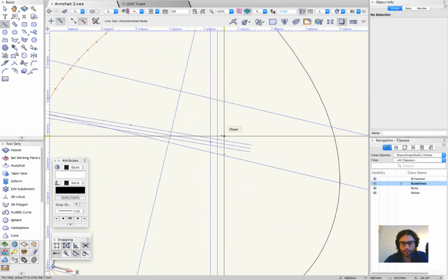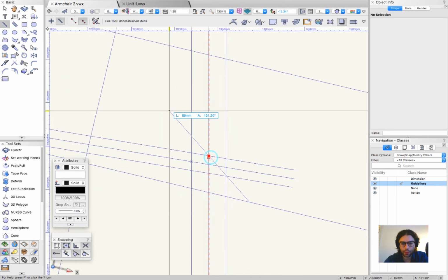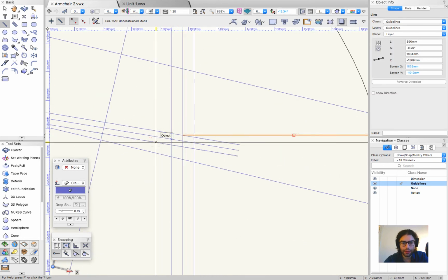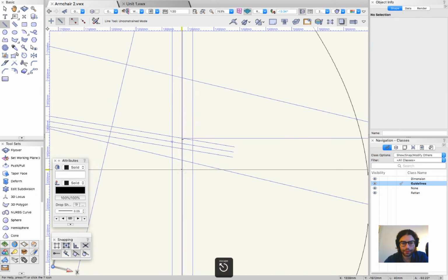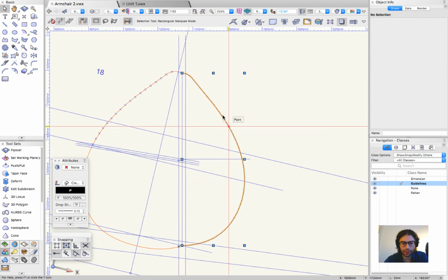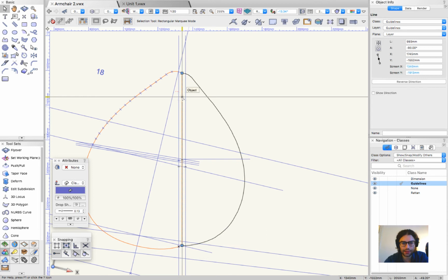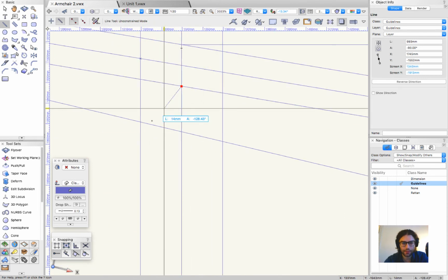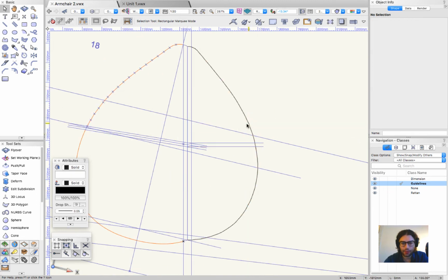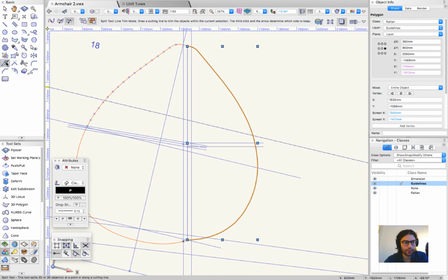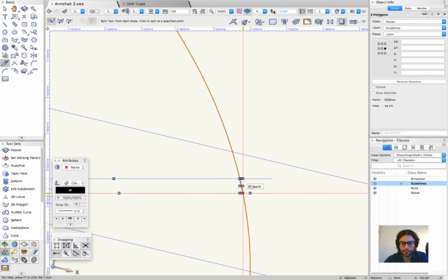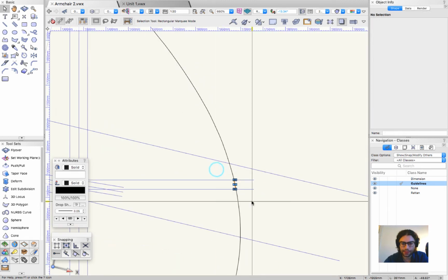Yeah. Now we'll do the following. We will project the intersection of the offsets and the projected section, I mean this one. This projects to this line. So we need to find these 2 points. And now I want to cut the projection using the point cut option. We don't need this small piece. Let's delete it.